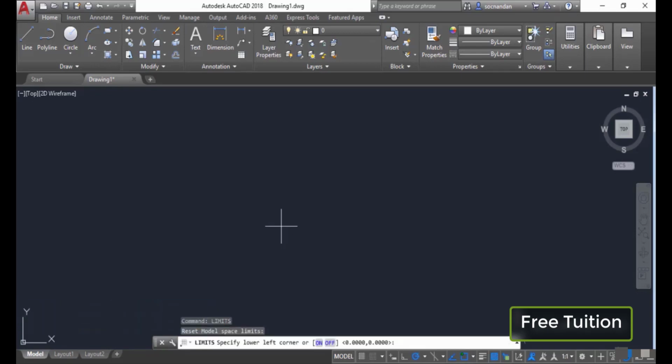Now this will prompt you to specify the lower left corner, which is 0, 0 in this case. So simply type 0, 0, or you can directly press enter, because the value in the angle brackets is the default value that will be accepted if you directly press enter. So I'll now press enter, and now you'll notice the upper right corner value, and the upper right corner value is simply the coordinate values of this corner.